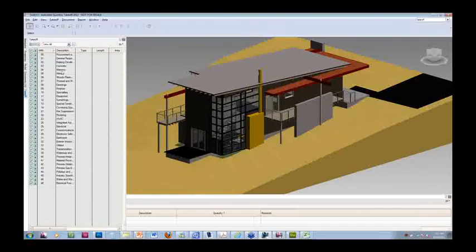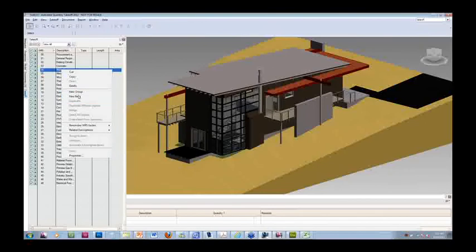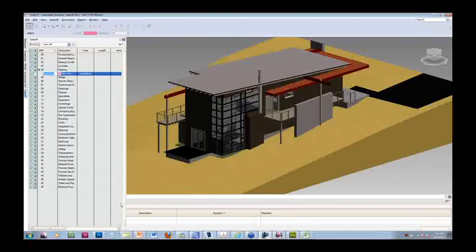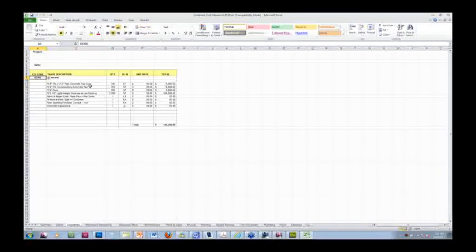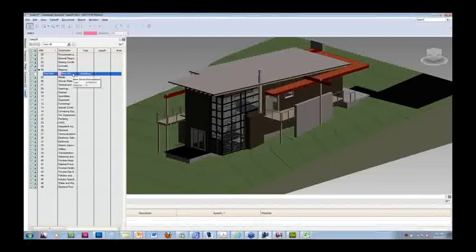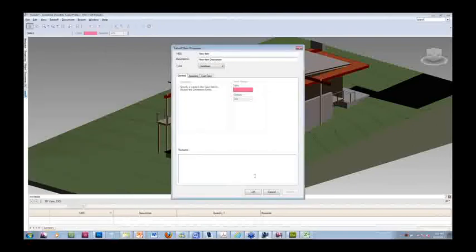So what that means is, watch this. This is the group. Right now this is kind of a starting point, so it doesn't have much. It's just kind of like a template. I'm going to create what they call a new item. Within that new item, let's say I use the spreadsheet as a reference and go to concrete. I can select that this is this particular kind of concrete wall. And then if I go back to QTO, I can simply give it a name.